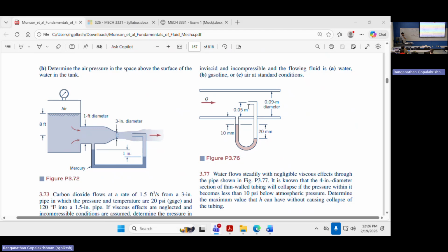So the fluid goes in and is brought to rest completely on the right side. And on the left side, the fluid is not directly captured or brought to rest. It just flows past it, but the static component is going to be sensed in the perpendicular direction. So what component of the pressure is felt here, and what component is felt here? Total pressure on the right and static pressure on the left.